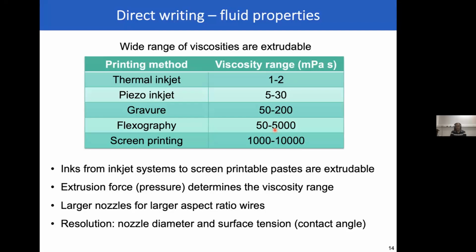So for example, if I just had pure nanowires, they will not work, because with pure nanowires you are going to have some sort of a gap, right? That's the whole idea behind using silver nanowires with PEDOT:PSS, the composite. We are able to reduce the roughness, but still the roughness is of the order of at least a few tens of nanometers, if not more. So to be honest, I don't have an answer as to how I would use silver nanowires as a bottom electrode. Potentially you can't, is what I'm thinking.